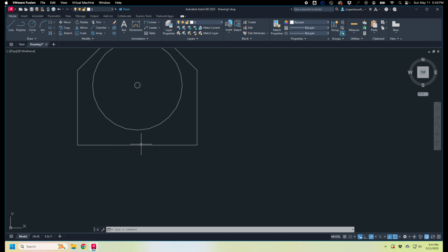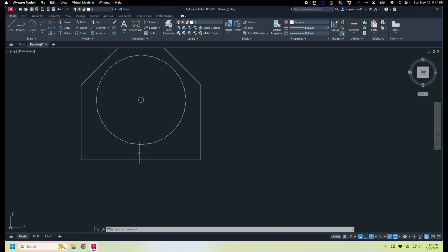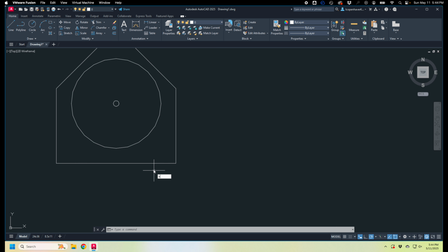So how do I figure out exactly where to put it? I'm going to bolt through a piece of angle iron through this plate that I'm designing right now. So how do I establish where that is? Well, I can put a line in there, like a guide. And because I want this thing to be really obvious that it's a guide, I might use a construction line or an XLINE. And this line can be horizontal, vertical, some kind of angle, bisecting, offset, whatever.